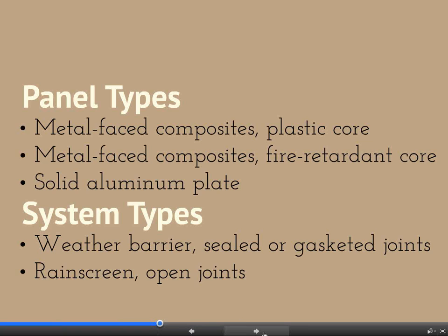But he does talk about rain screen systems. If you have open joints, that means that the cavity insulation needs to be UV resistant, since it can be exposed to sunlight. Rather minor, of course, because you have fairly narrow joints, normally usually 3/4 of an inch or so wide, and by the time you return the panels back in, there's not much light that's going to hit them. But what you do need to think about is that insulation being UV resistant, and are we going to like the color? Is it too light? I know that Rockwool, the mineral fiber folks, make a dark version of their product specifically for open joint cladding systems.